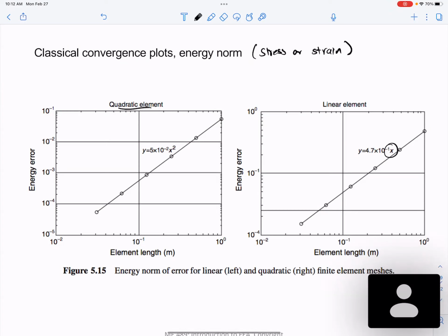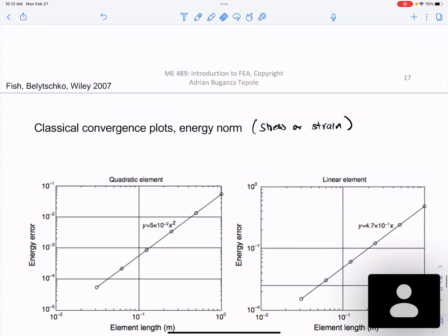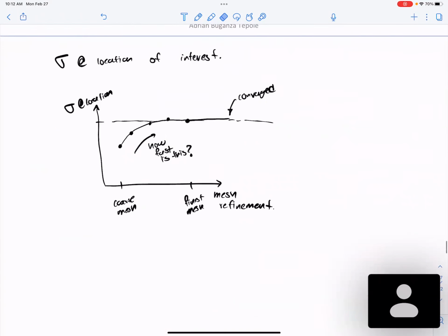For the quadratic elements, again, if you decrease your element size by half, the accuracy on the displacements goes up by 8, but the accuracy on the stresses only goes up by 4. So the square. This is just to give you an idea of how you should get more accurate. Again, regardless of whether you use linear or quadratic elements, you should do this type of plot.